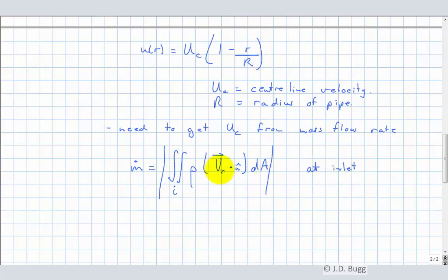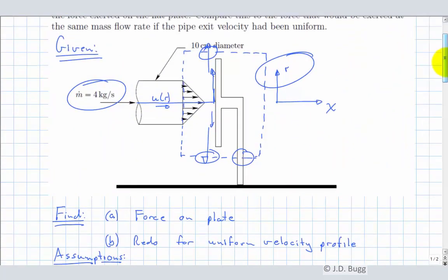Well, what is V_R dot N? Well, we come back to our diagram here. The unit normal at that inlet looks like that. Okay, always projecting out of our control volume and into the surroundings, perpendicular to the control surface. Well, this velocity that I've been solving for is in the negative n_i direction.